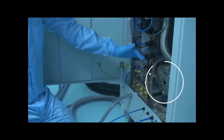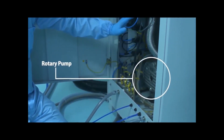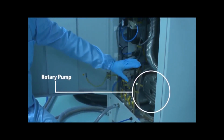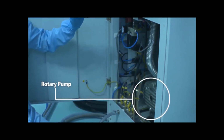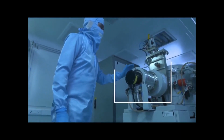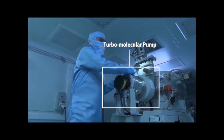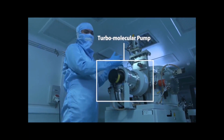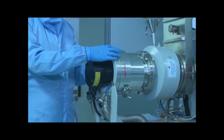This is our rotary pump, and this pump will bring down chamber pressure from 10 to the power 3 millibar to 10 to the power minus 2 millibar. So when the chamber pressure reaches 10 to the power minus 2 millibar, the turbomolecular pump will start. So this is our turbomolecular pump, and it can bring chamber pressure up to 10 to the power minus 6 to minus 7 millibar. We have to do deposition at 5 into 10 to the power minus 6 millibar. So it takes around 3 hours.